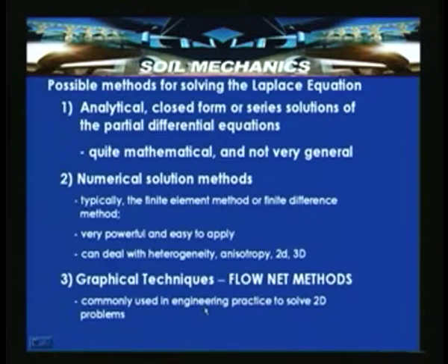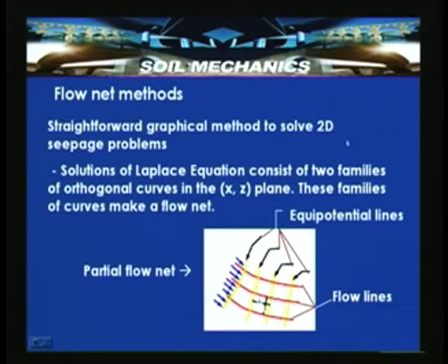So, flow net methods are basically straightforward graphical methods to solve two dimensional seepage problems. Solutions of the Laplace equation consist of, basically, a flow net, which means two families of orthogonal curves in x and z direction, and these families of curves are called a flow net.